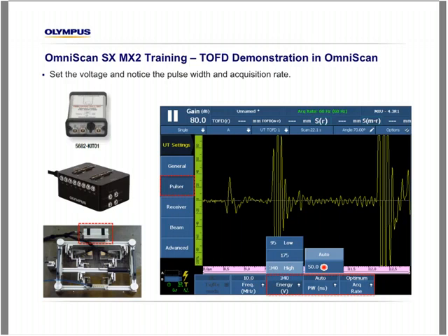The frequency of the probe was set during the wizard setup operation, and it automatically configures the pulse width appropriately. 500 divided by the frequency will be our pulse width we need for both shear wave and L wave inspections. This can be fine-tuned here or just left with the default. The acquisition rate should be under optimum. The TOFD group uses a single A-scan and a very small data file, so we need not increase this much faster than we need for the scanner to minimize the noise.